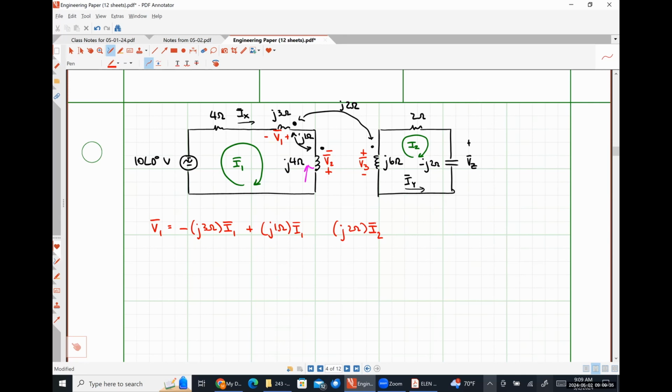So just to rehash things, the positive polarity terminal of the voltage V1, the voltage that we're trying to find, is at the dotted terminal of coil number 1. Has been every single time. The current I2 is flowing into the undotted terminal of coil 3. So that means this should be negative. Oh, here, look up there. That's undotted.